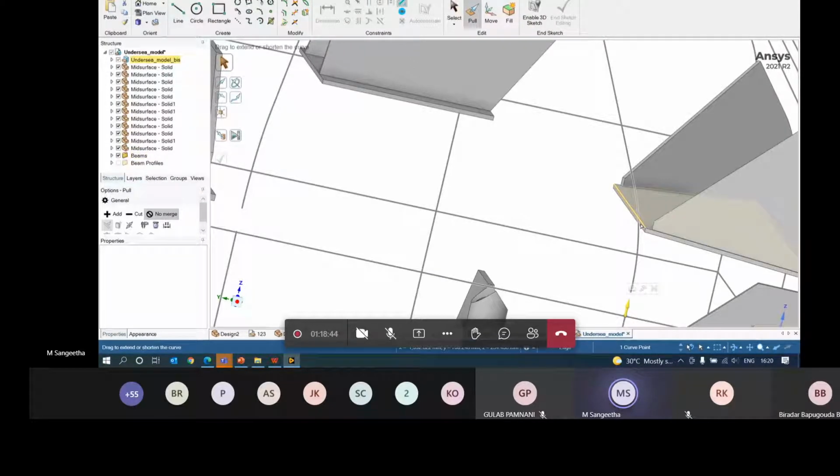Select this edge. Now if you do curve one, then curve extension will create it. You need to take a flat line, whichever is there, and go with "up to" and select this one, so that you are able to convert it. In the same way, here you can use extend, like "up to", and this is extended. So in this way, you have to extend all of this.